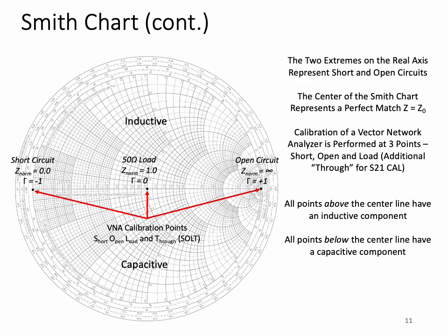Well, that's a vector of zero length whose origin is the center, and that corresponds to the centermost point on the Smith chart. For an open circuit, you can see that gamma becomes plus 1, and that's a vector of unit length, which is at an angle of 0 degrees, and that corresponds to the rightmost point on the Smith chart.